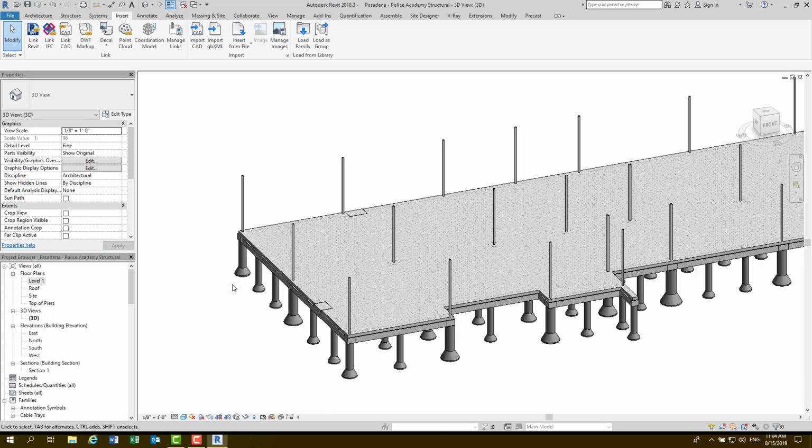Now it's just a matter of figuring out what elevations those are supposed to go at. So I go back to the drawings, and I got to look and see what it says for the bearing elevation for these things. Okay, so bearing elevation for this one is at 15. That would be in the top right corner. And it looks like it does that all the way across because it slopes from the front to the back.